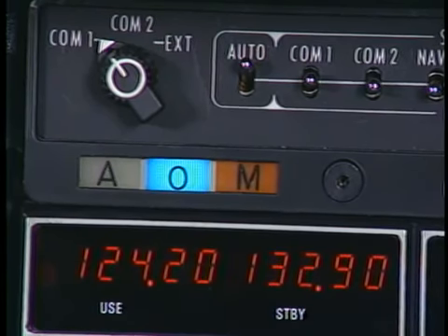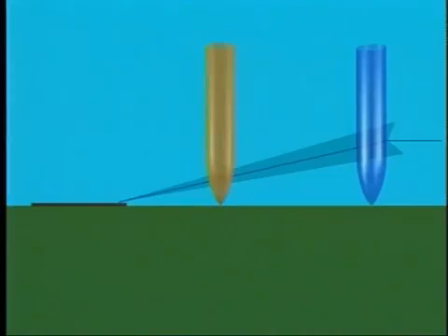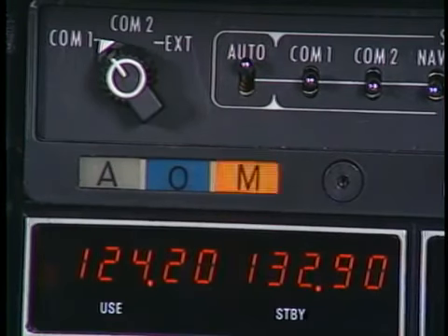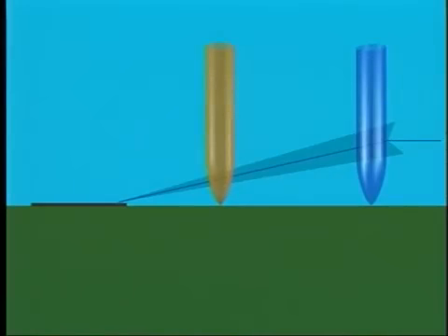A receiver in the airplane provides both an audible and visual cue when you pass over a beacon. The outer marker is identified by a flashing blue light and a continuous series of dashes. The middle marker is usually placed 3,500 feet from the landing threshold and intersects the glide slope at approximately 200 feet above the touchdown zone elevation. The middle marker is identified by a flashing amber light and alternating dots and dashes. Some approaches incorporate an inner marker that is identified by a white light and a series of dots. It allows certain qualified operators to fly an ILS approach to lower than normal minimums.